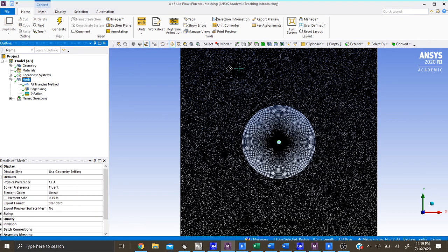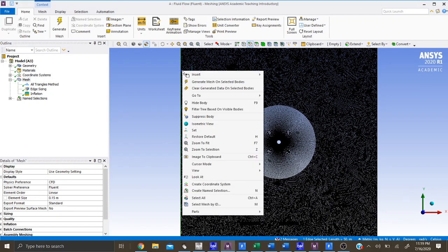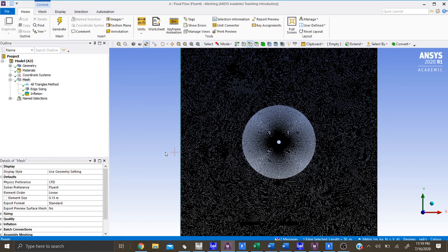Then our last step here was to grab our edge tool and name all the edges. You just click on it. I hit N, which quickly pulls up the selection name, but you could also right click and hit name somewhere in here. I don't see it right now, but I'm limited on time, but that's the other way you would do it.